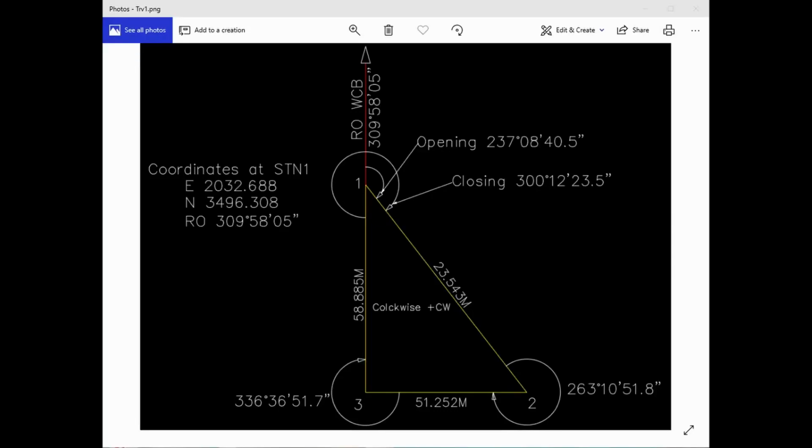In this video I'm going to be discussing a new procedure that I've just added to the SurvEngCalc app, and that is a closed traverse procedure. This procedure will calculate all the necessary reductions to get finalised Bowditch corrected coordinates.